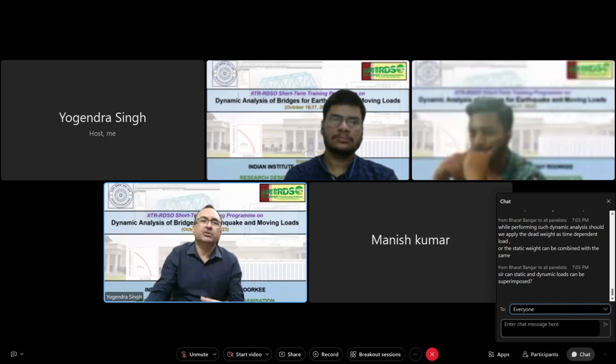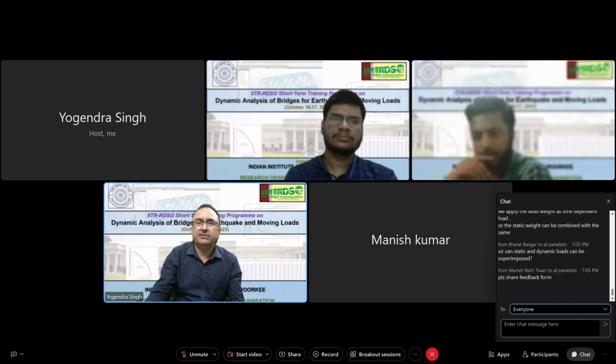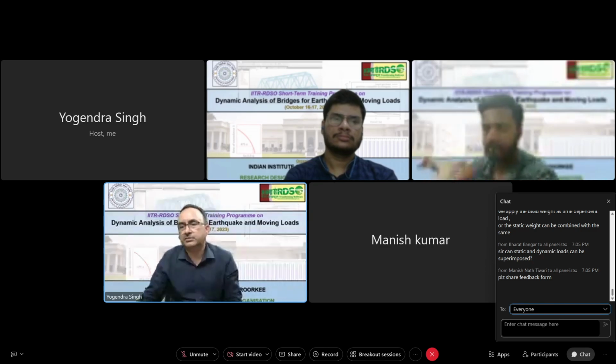But in this course, we have not talked about nonlinear time history analysis, so I don't think the question is related to that. So in case of linear time history analysis or any method of linear analysis, whether this is mode superposition or otherwise, we can first perform static analysis for dead load, and then we can perform a dynamic analysis for live load, and we can combine the results.